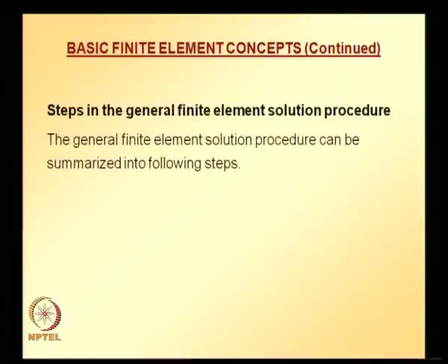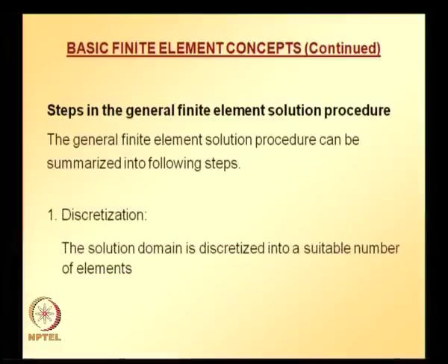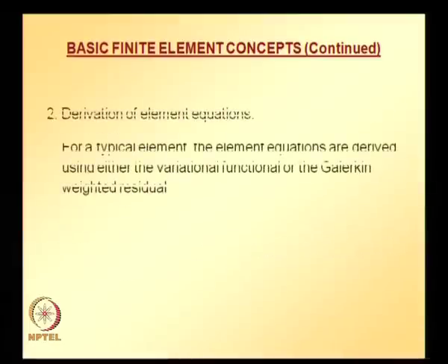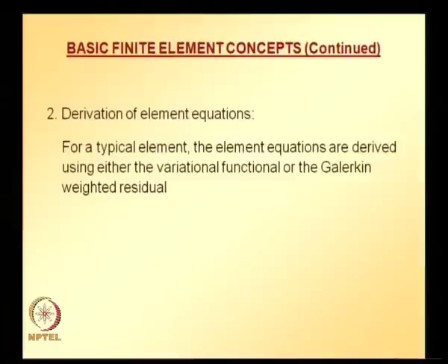So, the first step is discretization. Solution domain is discretized into a suitable number of elements, and derivation of element equations. We will do it for a typical element. Element equations are derived again using either variational functional, or Galerkin weighted residual.